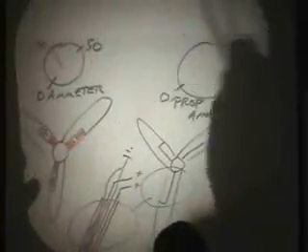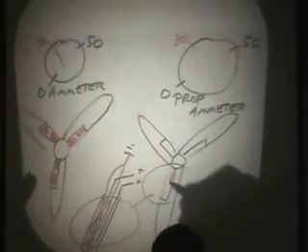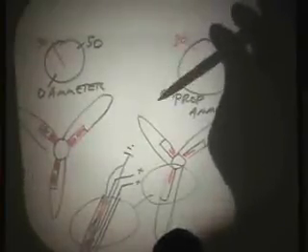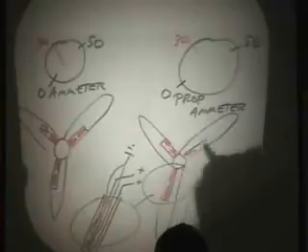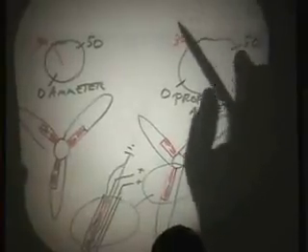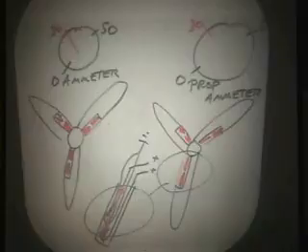It'll stay there for about 30 seconds, and then it'll go to 0. Then if you're watching these gauges, the other propeller ammeter will come up to about 30, and the inboard heating elements will get hot for about 30 seconds. It'll go down to 0 for a second or two, and come back to 30, and then the outboard heating elements will get hot. After 30 seconds, it'll go down to 0, and then the other propeller will start all over again. So it takes about 2 minutes for this cycle to occur.